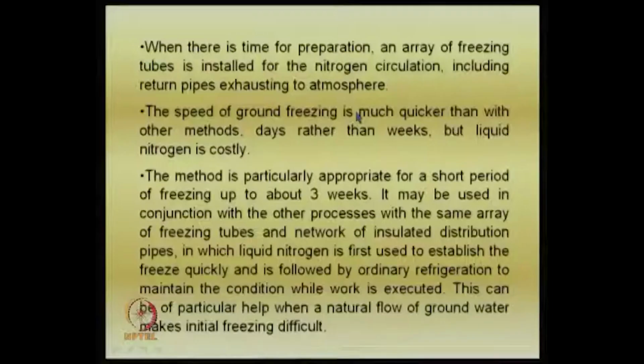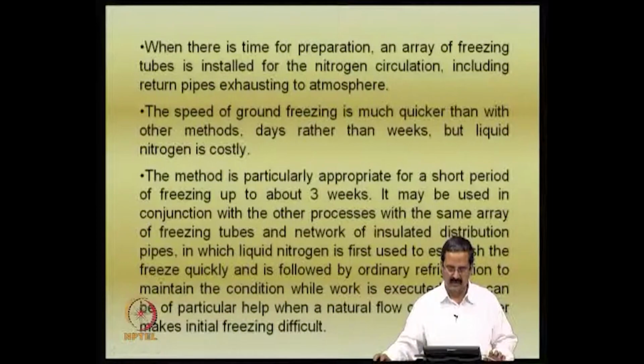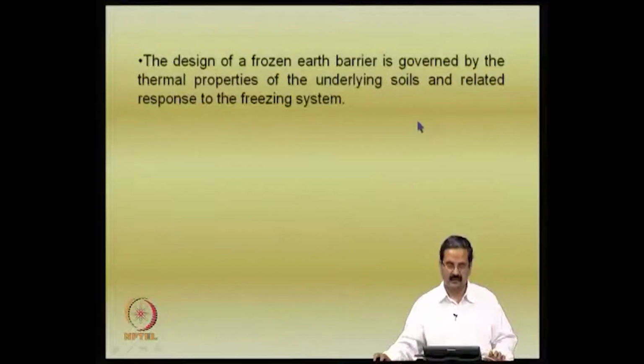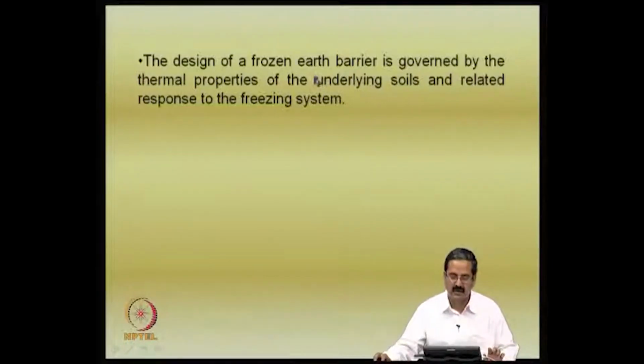So, as I just mentioned, the use of this freezing technique is something very tricky, and one should be able to design the system in such a way that you have a proper combination of primary cooling and secondary cooling systems, and also see that the circulation of coolant is proper, and also that the so-called frozen earth barrier is maintained till it is required.